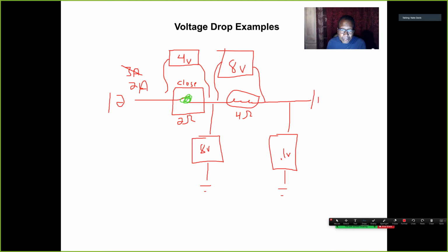Imagine if this point was a connector going to the coil. Instead of getting full system voltage, I have 8 volts. And guess what? At idle, it may work fine. But under load, since it's only 8 volts and less current, that coil may not saturate fully and have a misfire under a load. You see the comparison here I'm trying to do? You understand what I'm trying to do here?